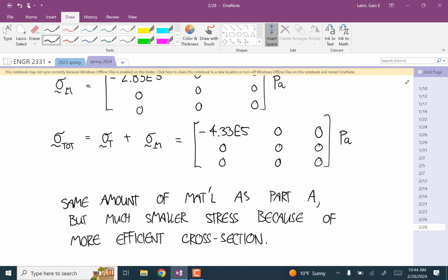And then the second question: I don't see why it wouldn't, but would this still work if, let's say, our T-beam was sideways, so it's kind of like that? Yeah, we can't do that because of the 4 requirements for this calculation of stress due to bending moment. Was it 4 or 3? I have to think about them, but it has to be straight, it has to be prismatic, and it has to be symmetric about the y-axis. So that's the one that it fails, yeah.